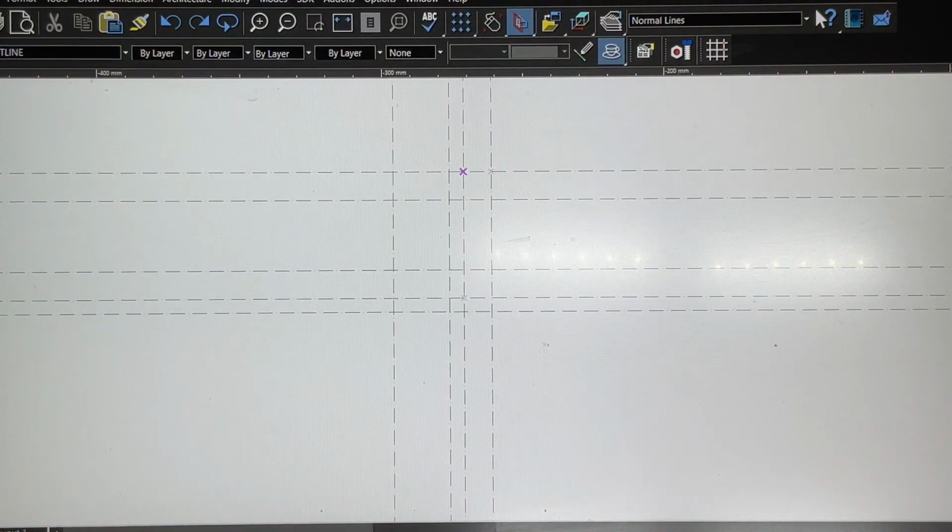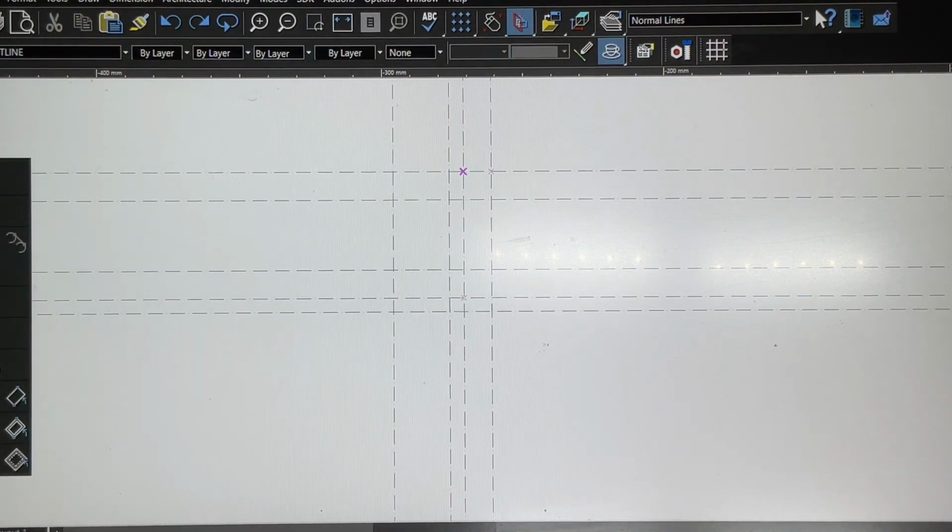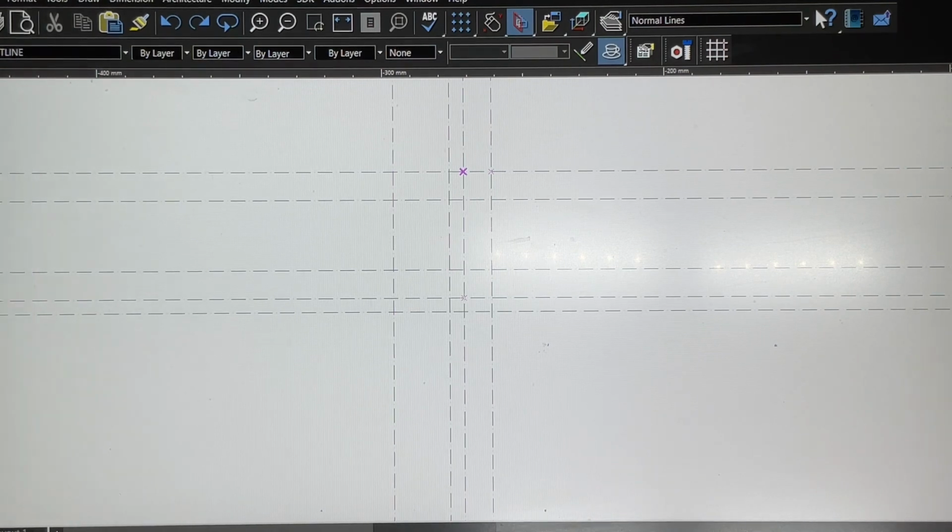If you've got that and you're going to draw a line, you should find that drawing the line, nice long left click on the line, go into the point, and you'll see that it should snap onto that if this little thing down at the bottom that says snap has been highlighted.